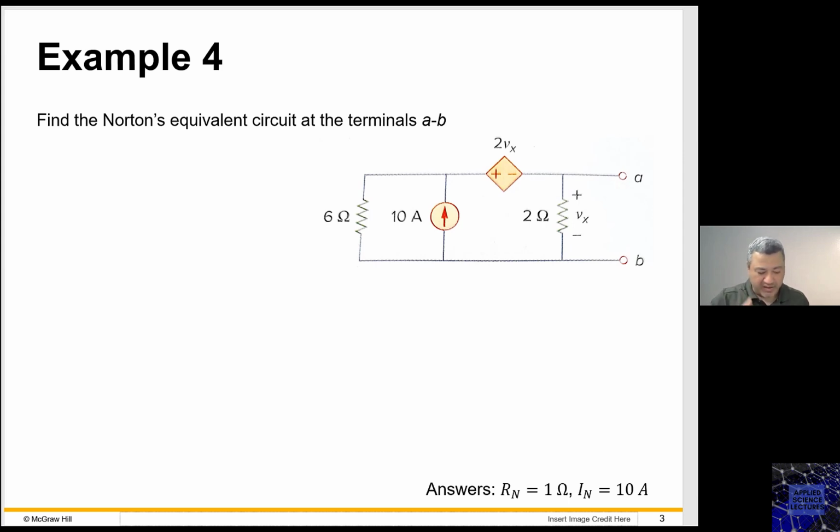You have to do something different. You have to either add a voltage or a current source at the output, or you can still look at the general approach, which is calculating the open circuit at the output and calculating the short circuit at the output. Then R Thevenin and R Norton would be basically the ratio between the V open circuit to I short circuit. So this is a second approach that we talked about, and we said that we will see it.